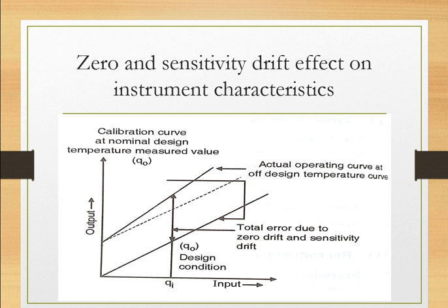Stray electrostatic or electromagnetic fields can be prevented from affecting the measurement by proper shielding. So you have to do proper shielding so that we can reduce or prevent electrostatic, electromagnetic or stray magnetic fields. So proper shielding is one option.